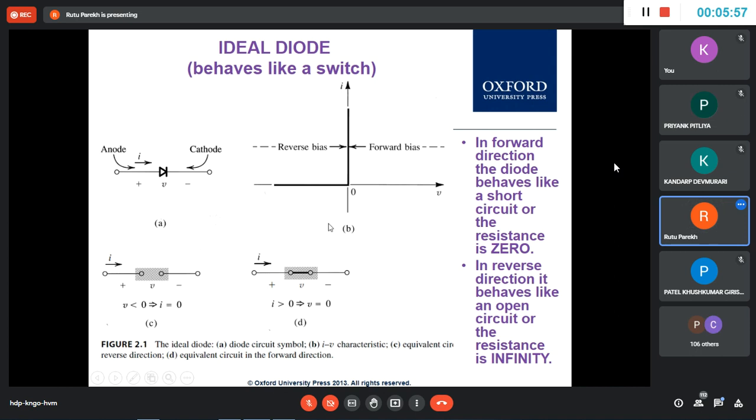It's a big class. As he said correctly, we are using different models. The diode operating voltages are small, less than about 0.7 volt when you use the current equation. When it is on, it is 0.7 or 0.8 volt; it is not a 3, 4, 5, 10 volt device. When you are working with high voltages, and the drop across the diode is comparatively very small, we use the ideal diode model as a first step of analysis, although nothing is ideal in the whole universe. Step by step we will see other models also.